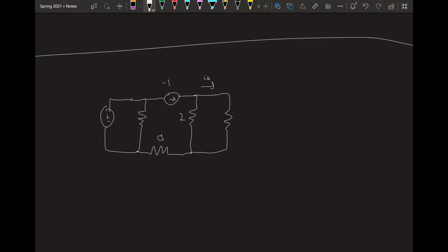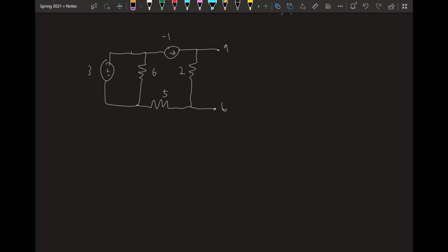I/O is gone. This is our circuit now. We're going to solve for a Thevenin equivalent and then put R back in, and it'll be the exact same thing as if it was there the whole time. So let's solve for V Thevenin now. Remember, the circuit is an open circuit, or it looks like that, so we can solve normally.